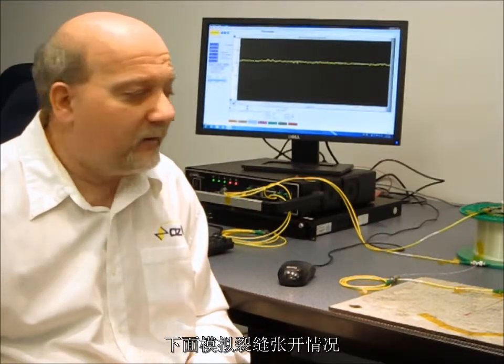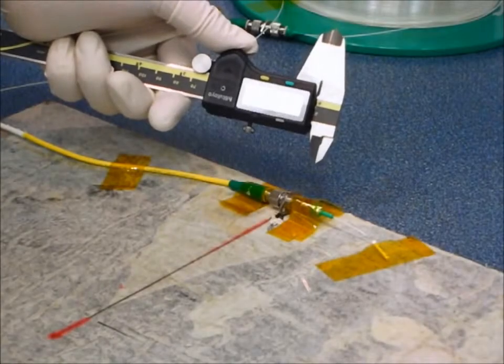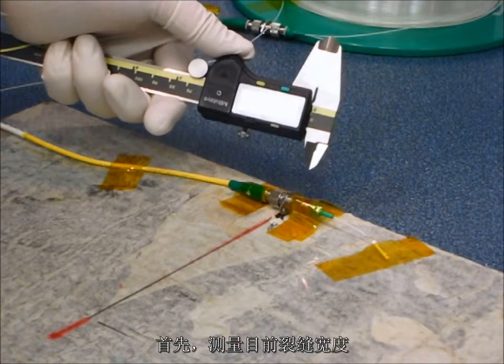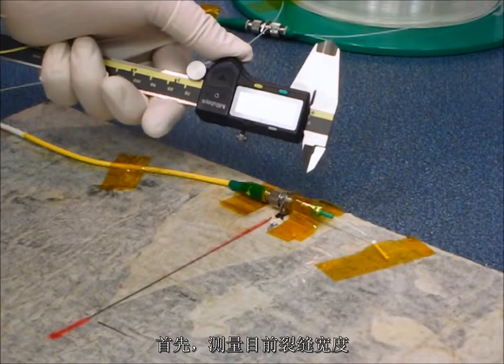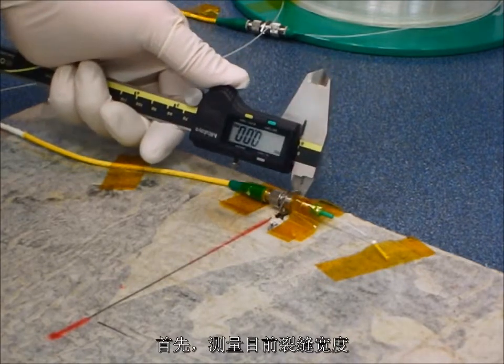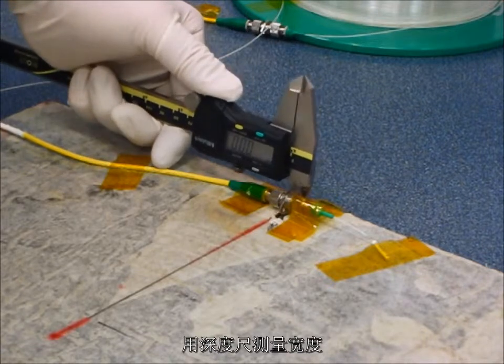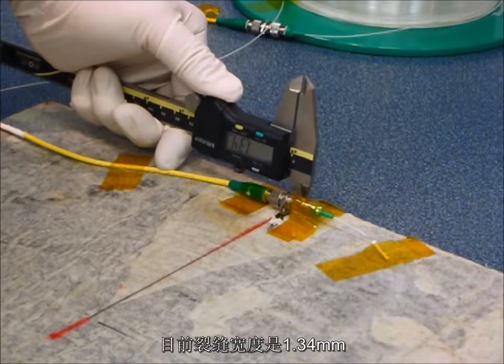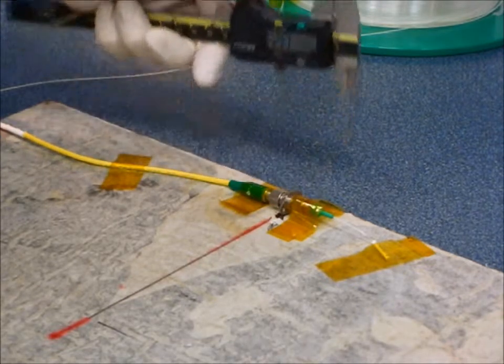So let's now start simulating the development of a crack in our setup. Alright, so to begin, let's measure the initial width of our gap in our plastic sheet here, and then widen it and show the difference. So, using a pair of calipers, we're making an initial reading, and it's reading 1.34 millimeters in width right now.